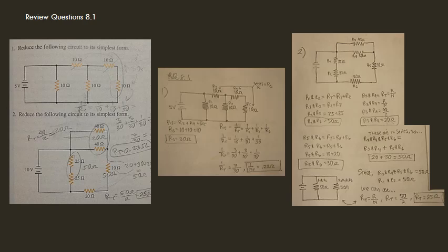In this case, we have 10 ohm resistors for all 3 instances. So we add 10 plus 10 plus 10, which is 30 ohms. So we make R5 into 30 ohms. And we can just for now omit the other 2 resistors, which are now combined into R5, which is 30 ohms.